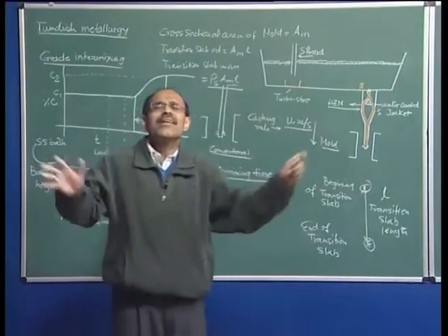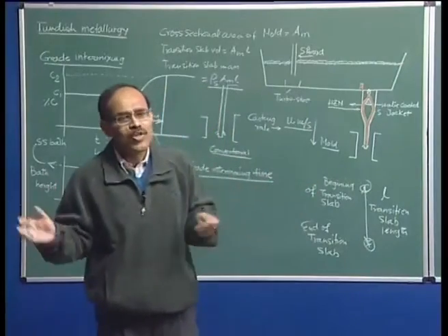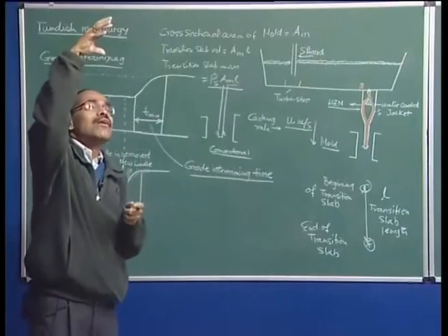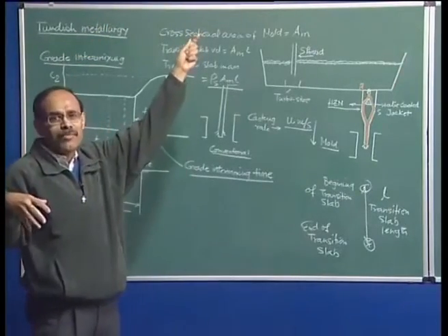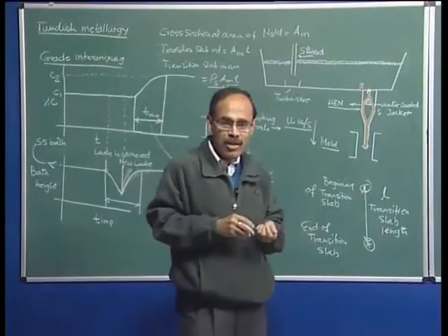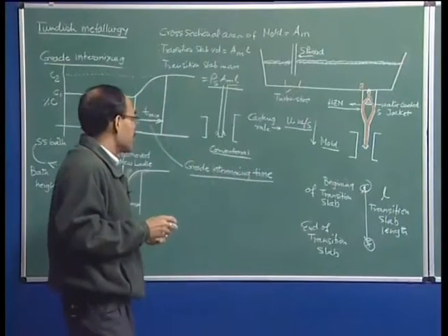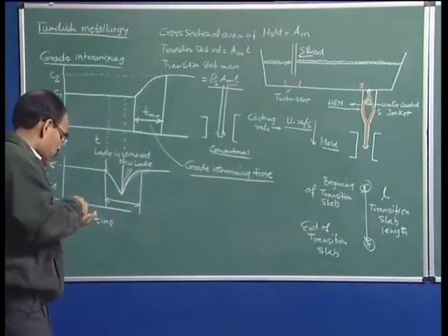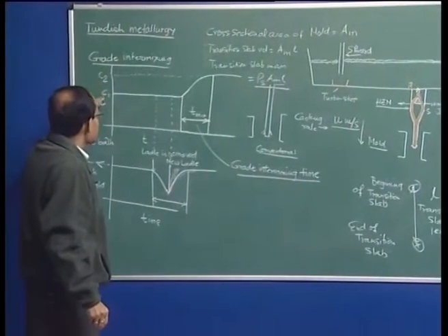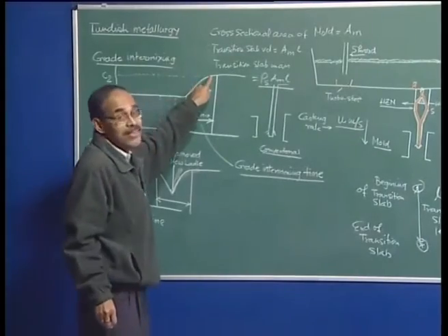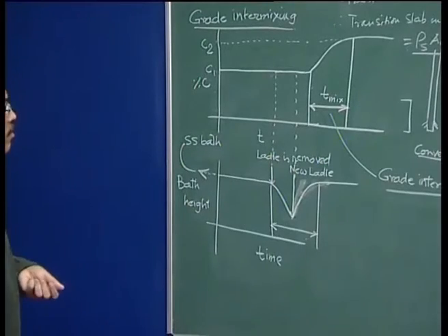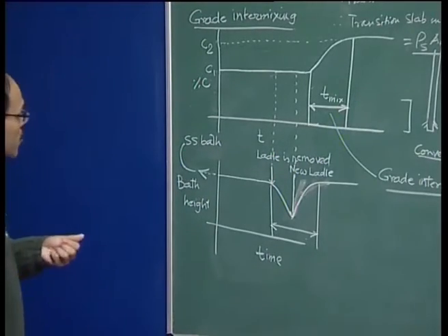If you are casting primarily plain carbon steel, it is not such a big deal, because if you are casting 0.14 percent carbon and 0.28 percent carbon, you will always find a buyer who will take that intermediate composition of carbon, but it is not true when you are particularly making alloy steels. So, how do you understand this? How do you generate this curve? This is a very important issue. This can be done by modeling, which we will be discussing, or demonstrating, through a few lectures.